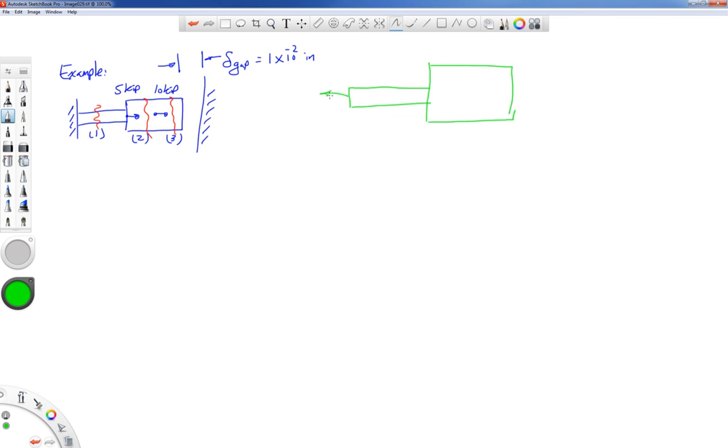Let's call this FA for point A, and over here point B, let's call this one FB. We've got our 2 applied forces of 5 kips and 10 kips at those locations. So the overall free body diagram says minus FA plus 5 plus 10 plus FB is equal to 0.